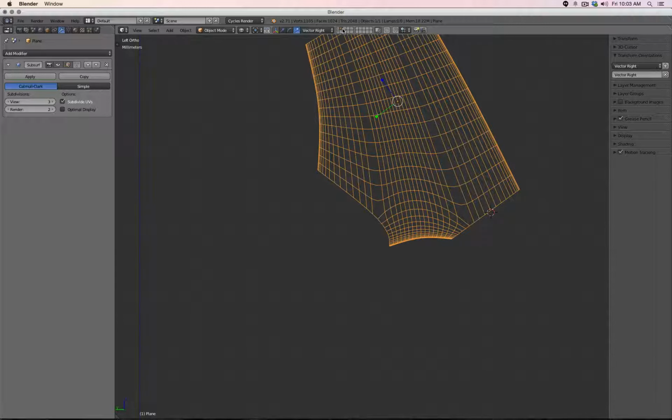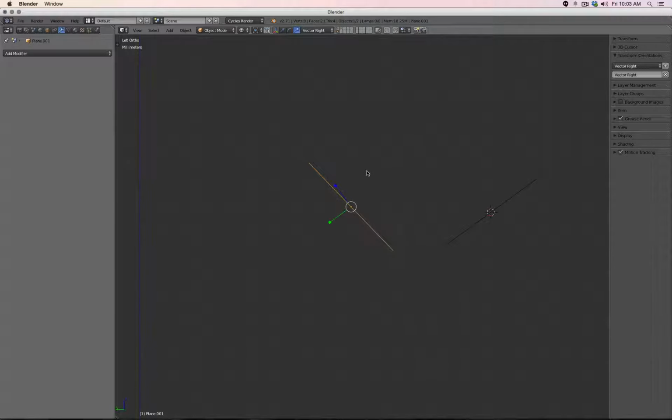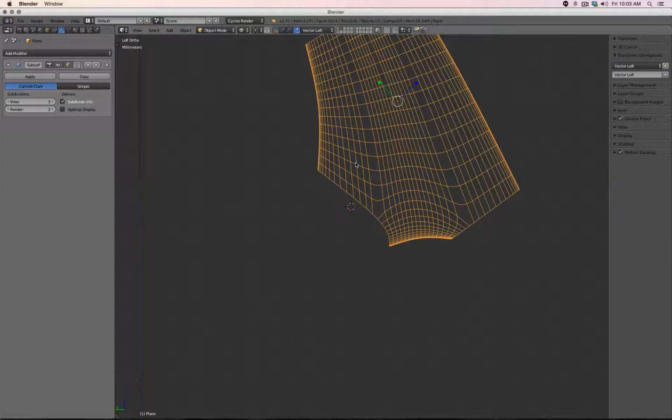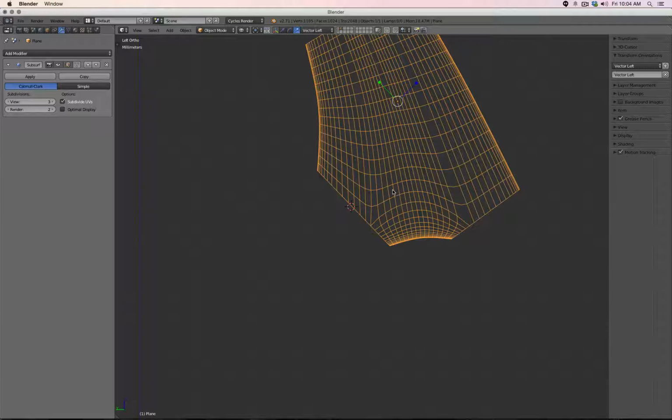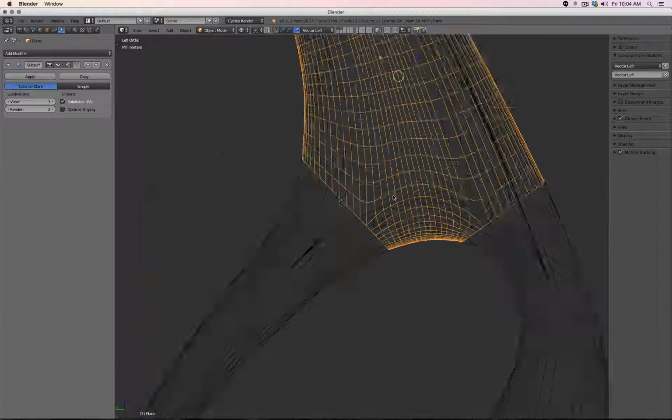They're all aligned now. Go to here, this plane, the correct vector, Shift S, cursor to selected, go now to my object, go to edit mode, select only the needed points, S, Z for global, Z again for local, 0, enter, and let's compare.